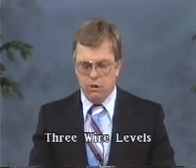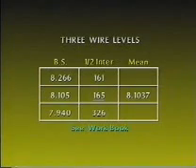Our next example of level notes illustrates differential level notes for 3-wire levels using a foot rod. 3-wire levels is a method used to obtain higher accuracies than normal differential level procedures. In our example, the first set of backsight readings represents the readings on the rod for the top, middle, and bottom crosshairs of the level scope when sighting the rod. 8.266 is the top crosshair reading, 8.105 is the middle crosshair reading, and 7.940 is the bottom crosshair reading.